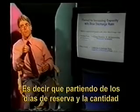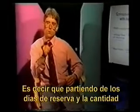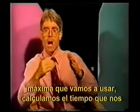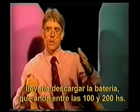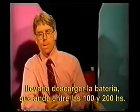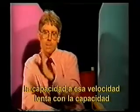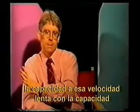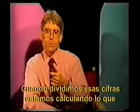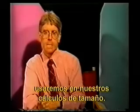So what we're able to do is calculate from our days of reserve and the maximum amount that we're going to use, the amount of time that it would take us to discharge our battery. Typically, this turns out to be 100, 150, 200 hours. We then look at battery literature and can compare the capacity at that slow rate to the capacity at the manufacturer's standard rate. When we divide those numbers, we'll calculate what we've called a rate factor, and we'll use that rate factor in our sizing calculations.